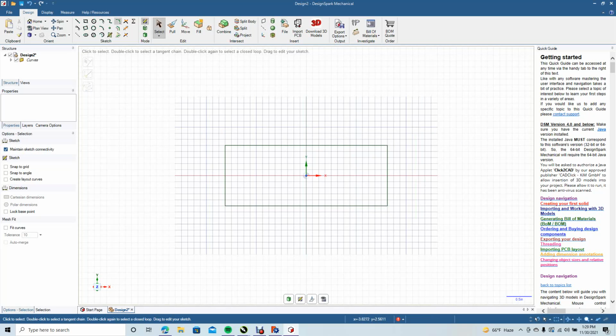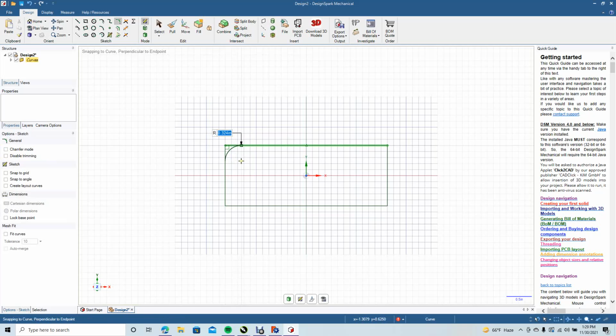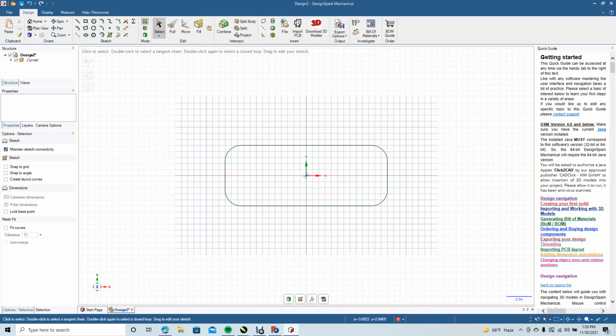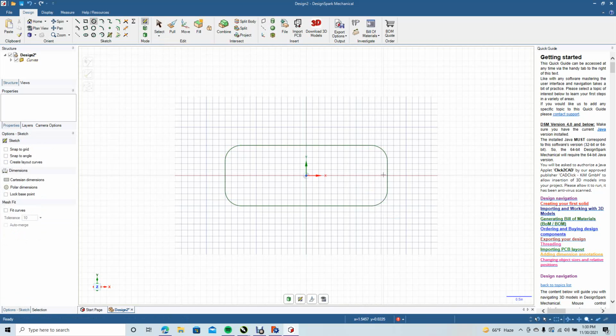We're going to round the corners with our corner rounder feature. Go 0.324. Do the same over there. Okay, that's going to be our base. So now we're going to put a hole there to actually put our keychain through. So 0.225, that should be big enough.